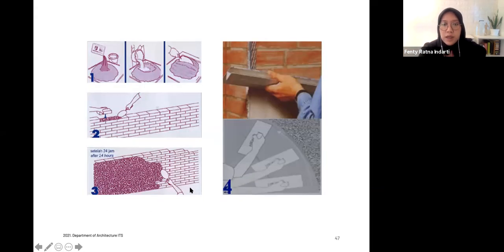This is another type of construction process, which we call wall finish. In the beginning, you create the mixture made from cement, water, and also sand. It's probably 1 to 2 or 1 to 3 in the ratio, but I don't think that you need to practice on it. Usually the craftsmen understand, but you have to understand the quality of the mixture, so that you make sure it is a good one. The element can perform well and can fulfill your intentions.